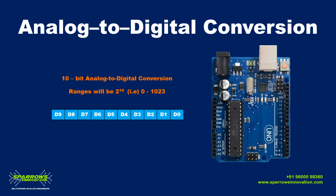Whatever voltage you provide at the analog input pin will be converted into a value from 0 to 1023. That means overall the total number of values is 1024. The reference voltage will be 0 to 5 volts. So 0 volts will be a value of 0 and 5 volts will be a value of 1023, right. If you are going to connect any sensor, you have to apply these values read by your analog pin to their respective formulas.